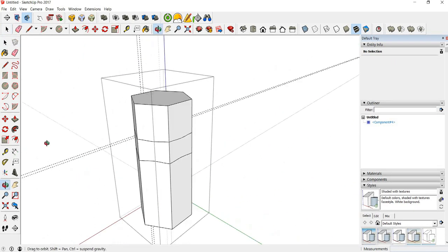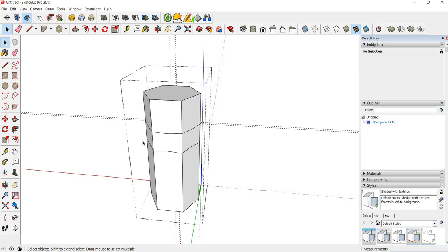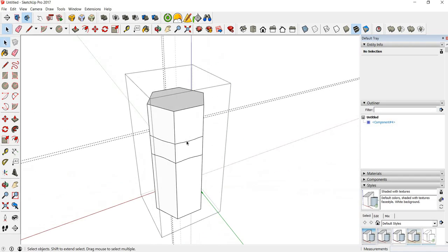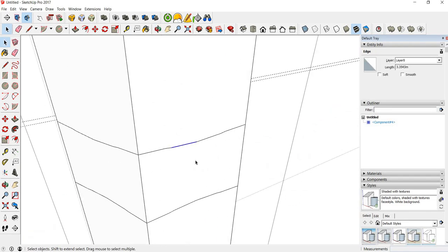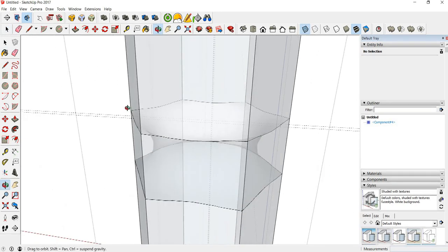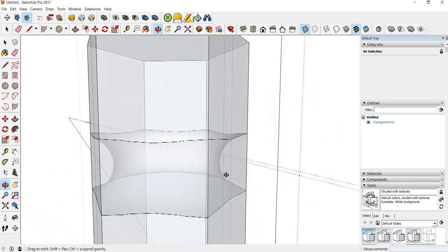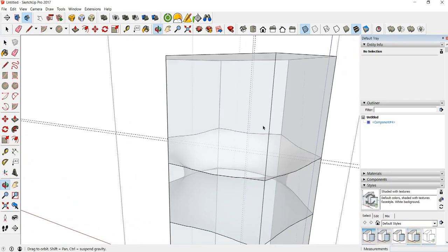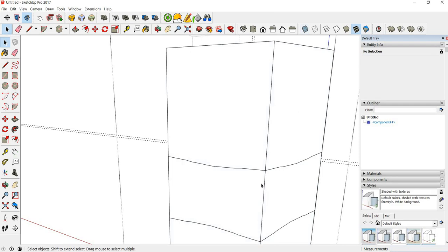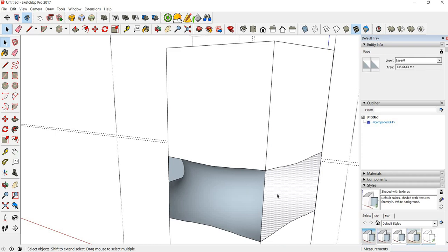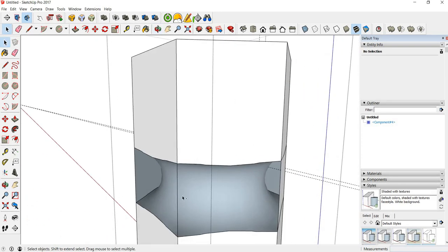And notice it's left this interesting shape all along this right here. So I'm going to zoom in. I'm going to click that. Now if you remember last time I said if you click on a boundary and you delete it, it breaks the shape. That does nothing for us. So X-ray mode to verify that there's some sort of pattern in there, and there is. So let's figure this out. We can delete each individual face, and I'll show you, it'll leave this line right here, which is fine.